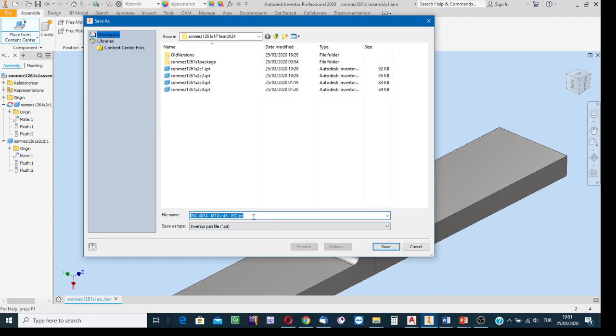Okay? Only for standard components at this file saving stage, do not change the file name. Keep it. It is just the necessary technical node in the form of the specification node for that standard component to write and to find in the parts list of the assembly drawing. This is important. Do not change the file name. Just click on the Save button.